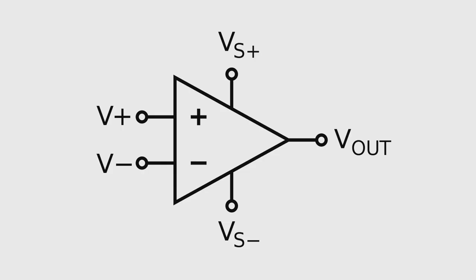An operational amplifier, often called an op-amp, is a DC-coupled, high-gain electronic voltage amplifier with a differential input and usually a single-ended output. In this configuration, an op-amp produces an output potential relative to the circuit ground that is typically 100,000 times larger than the potential difference between the input terminals. Op-amps can amplify both DC and AC signals.